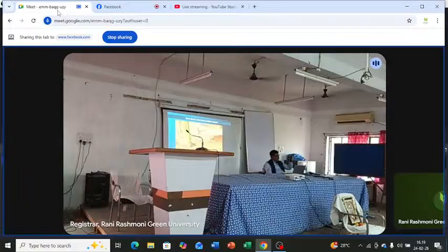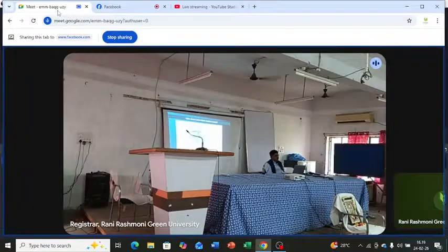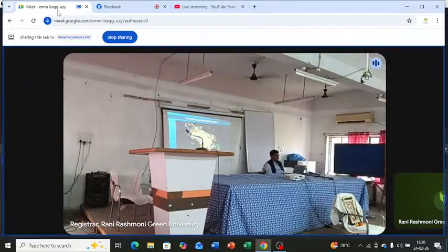It can be as close as maybe 0.5 centimeter by 0.5 centimeter. So what you are seeing is not an image, it is a point cloud embedded image. It also restores the color and texture of the image as well as the coordinate element. Now this is showing how the georeferencing takes place. Four scans from two different places are plotted together as the georeferencing is done, and there are different methods of doing this georeferencing to finally get a big, large model.